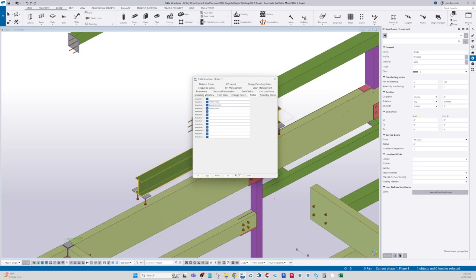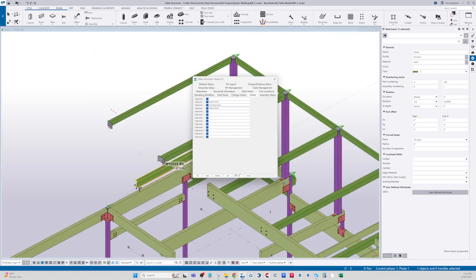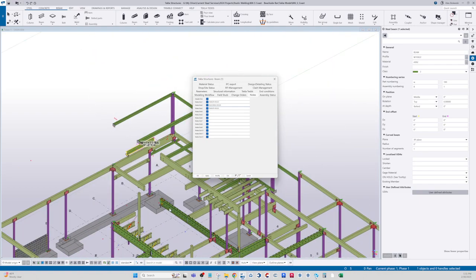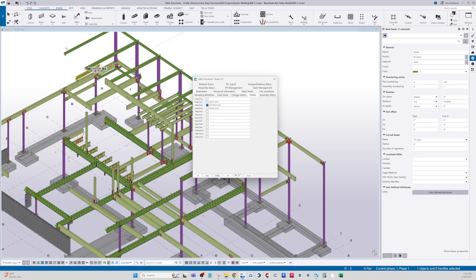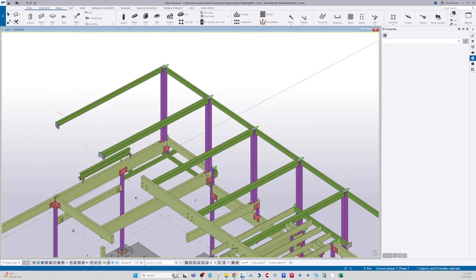And then blocking holes. And what you could do is you could just select all of the beams that you want blocking holes on. Select all of the beams that you know you want web blocking holes on, and just click modify. And then select all the beams that you know you want nailer holes on the top flange, and select modify for note 1, and then same for note 3. And then when you get into the drawings, you can just add a note